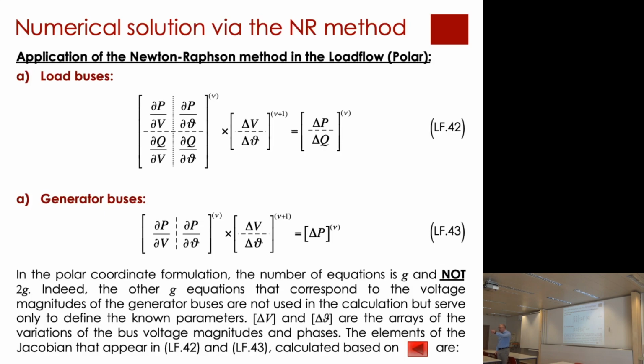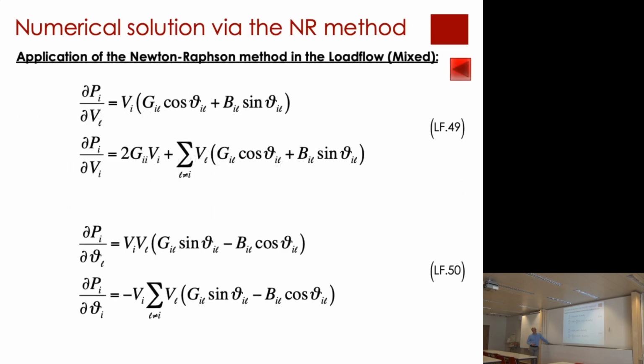So if you have one of the nodes which is weak, you can say how the voltage will change in this node by changing all the injections everywhere. It's a kind of sensitivity analysis. And this is how you redispatch the other nodal quantities if you have troubles. Okay, that's an example of how to use the Jacobian matrix to compute the sensitivity of a given state variable with respect to injections. Okay. Again, you will see applications of this in the fourth part of the course. Okay.